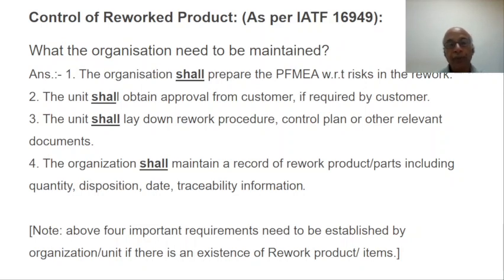So dear friend, what is the requirement to control the rework product? As per IATF, for rework parts, the organization shall prepare the PFMEA with respect to risk in the rework activity. The unit shall obtain approval from the customer if required by the customer.